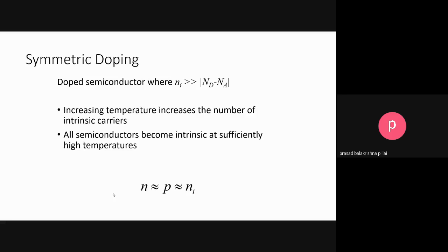So at room temperature and above, you will see that the carrier concentration will be increasing, and that will be the intrinsic region. So normally we will see that even though you will be using an extrinsic material, the conductivity and the band gap is measured because you will take it to the intrinsic region. So you have two separate regions.